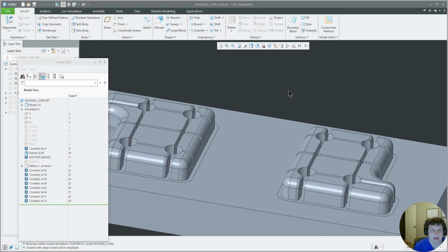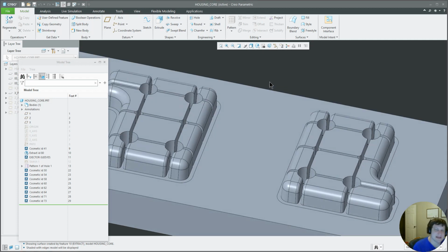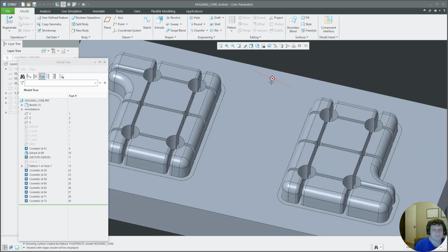Manufacturing Design. We're still working on this first injection mold. Right now we're talking about putting in the gate location, because that's something that's fixed and will affect our waterline placement and other features of the block.